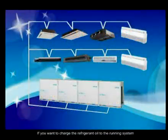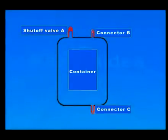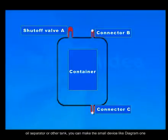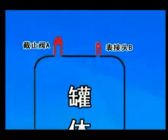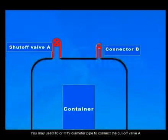If you want to charge refrigerant oil to a running system, you can try this kind of small device. Using a small refrigerant tank, low pressure tank, oil separator, or other tank, you can make the small device like diagram 1 and connect the gauge connectors at the upper and lower places. You may use Phi 16 or Phi 19 diameter pipe to connect the cutoff valve A.